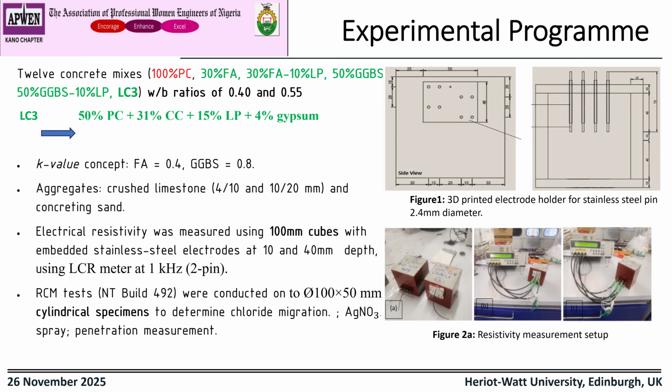During the hydration, there is what we call CSH. It will be produced in the concrete. Then there is what we call Portlandite. That Portlandite is highly alkaline in nature, and it is part of the hydration products. So when you replace the cement, it means you reduce the amount of hydration that will produce that Portlandite, so it will reduce the amount of Portlandite and reduce the hydration.